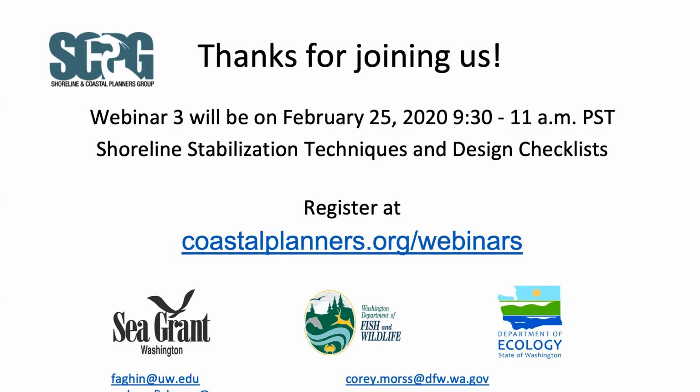And as I'm saying that, it reminds me, it's important to remember there's more variability on what local governments' SMPs say about repairs and replacements than there is about new or enlarged structures. So as I was covering in the slides, new or enlarged shoreline stabilization requires that geotechnical report. It requires that demonstration of need that has to be shown through a geotechnical assessment.